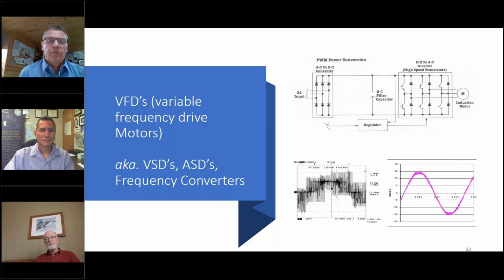So usually that float, those manufacturers would probably put a value of how much float there may be. I can't speak for every manufacturer, but we're talking about less than 5 millimeters of float, maybe a bit more than 5 millimeters, but could be 10 millimeters. Again, it depends on the length of the rotor and stuff like that. But you should have a mechanical indicator to show you where magnetic center is.